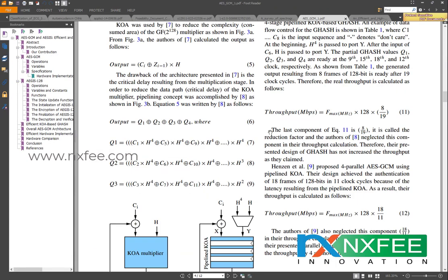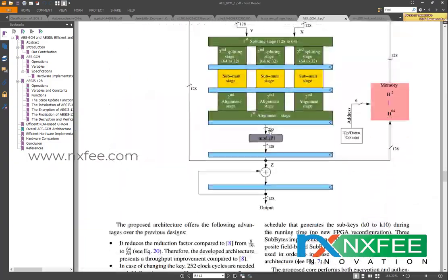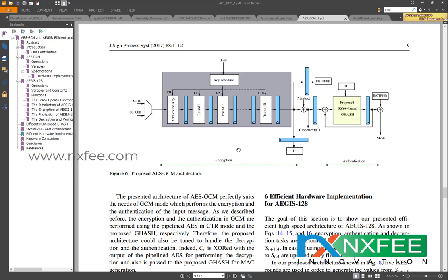The proposed parallel method is shown in Figure 6, and it is covered with the sequential technique method. Four parallel architectures means the AES architectures are used one by one. Four parallel architectures take more logic size, more power consumption, and more LUTs, LUT RAM, and flip-flops. For the one-by-one sequence of the AES-GCM method, the logic size, power consumption and so on are reduced. For this purpose the proposed architecture will be helpful.